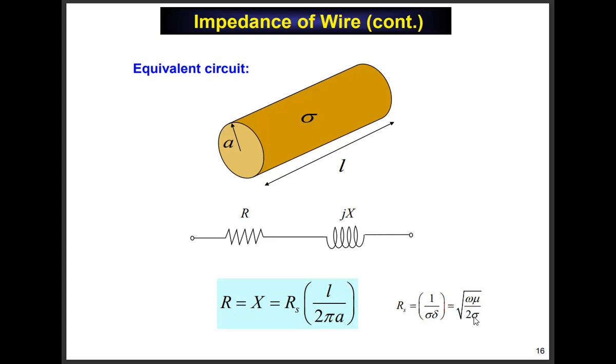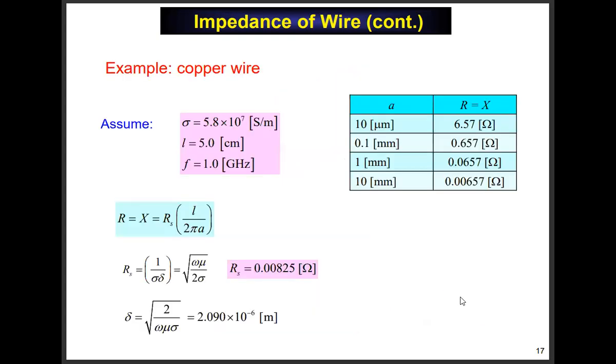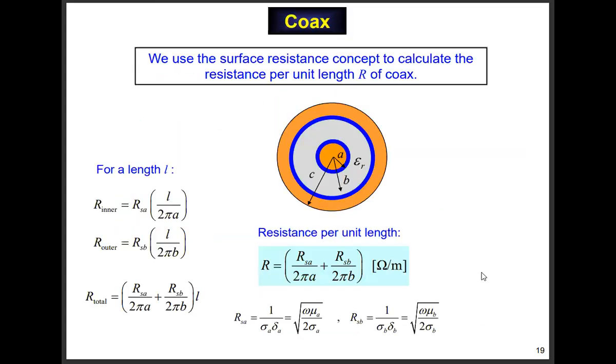It's 0 for a perfect conducting wire, but it also gets high as the square root of frequency. So again, wires at high frequency, like microwave frequencies, have much higher resistance than like a DC current flowing through a wire. And I showed you that table last time. Okay. Now with that in mind, let's go to the coax and apply our knowledge to the coax.